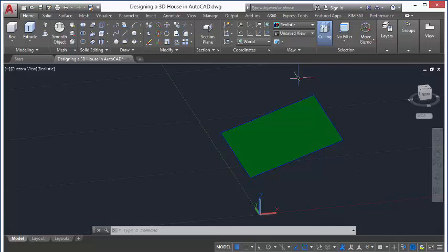As I was explaining, the overhanging on the slope side is 2 feet 6 and the overhanging on the gable or the lean-to side is 2 feet. So we want the fascia board to be 1 inch, then the overhanging to be 2 feet, then the other 5 inches to cover the fascia board.